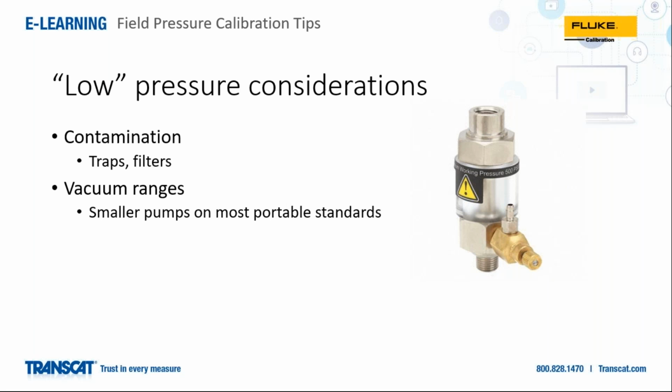So the calibrations in the pressure world all depend on assuming that the pressure that's being measured at the calibration standard is the same as the pressure that's measured out at the device. So if you have a restriction between those, that is not necessarily true.